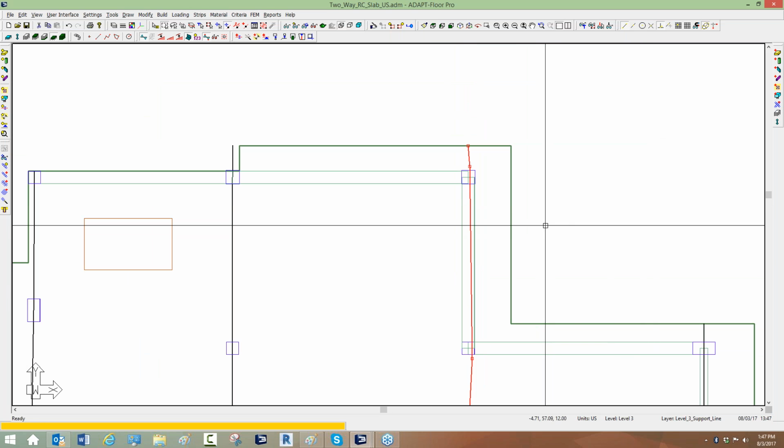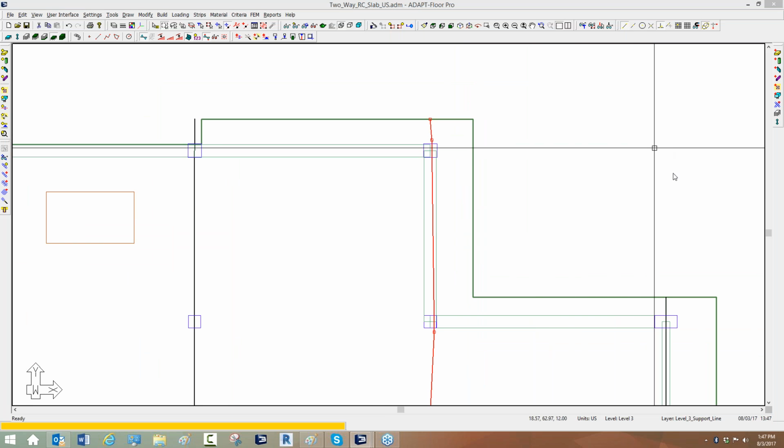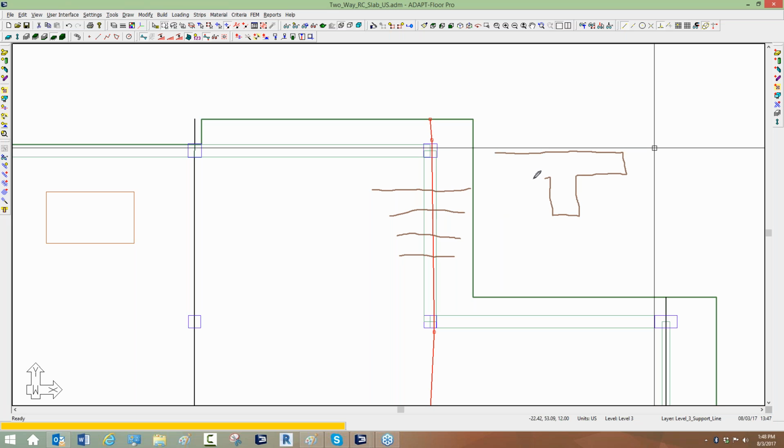Okay, from a design section standpoint, the design sections would look similar. You would get a design cut that goes through like so, and you think, okay, great, it's considering the beam, so the beam should look like this when it evaluates it. But in reality, because this point is not on that end of the beam, or this point is not on that end, or both, the actual section that the program designs for is a flat slab.